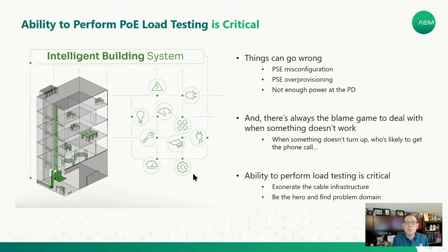You plug one device in, maybe it works okay. You plug another device or two in, and now all of a sudden you're starting to have problems with your PoE, and you don't get enough power out of that device. And then there's always the blame game. So that's where having a good troubleshooting tool will help. If your certification tester can also do PoE testing and the DC resistance measurements that we need to do, you're ahead of the ball game, especially with that PoE load test.